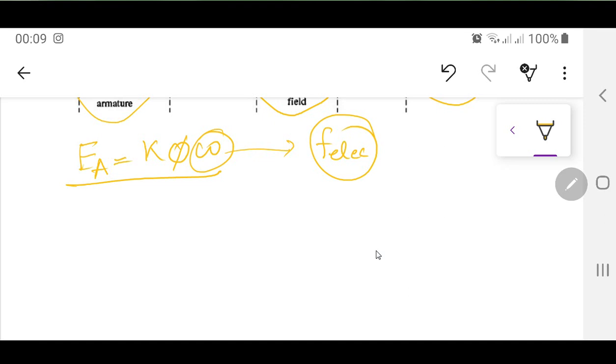So this is very, very important: the flux phi, which is being given to the rotor over here, in this case certainly by a pilot exciter or a brushless exciter, whatever that scheme may be. So this is very critical. By changing the flux, you can change the EMF. So EA over here is the induced EMF inside any of the three phases A, B and C.